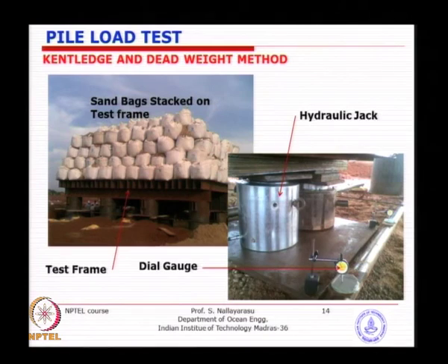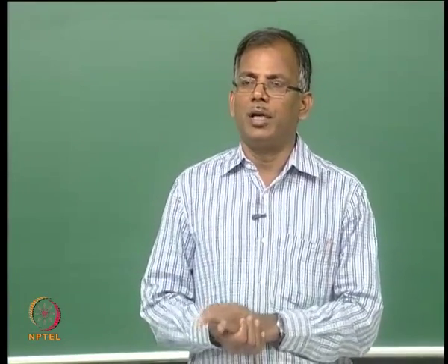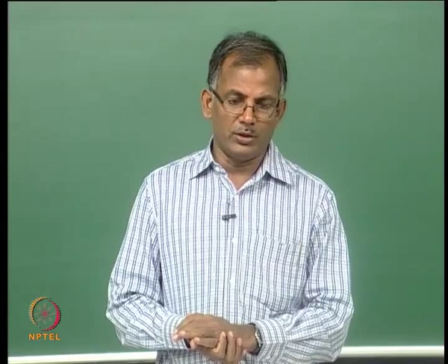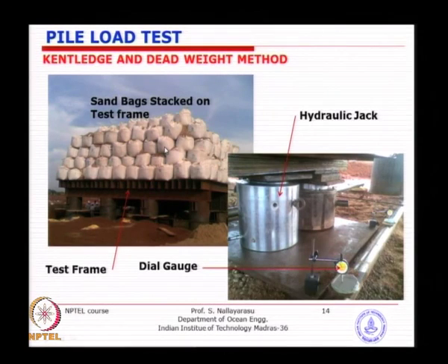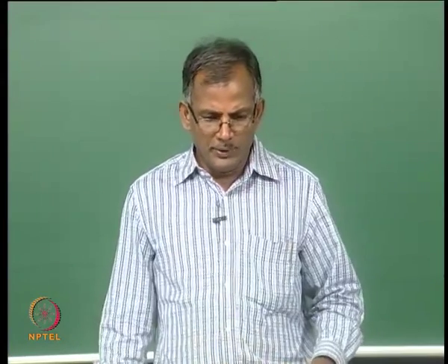So, we need to have piles going down to firm ground, because the top 15 meters of soil is a soft clay, and if you try to put some spread footing, it will definitely sink under this kind of support reaction load during stacking, and then you can't retrieve. Then every time you load and unload, the foundation becomes of no use.